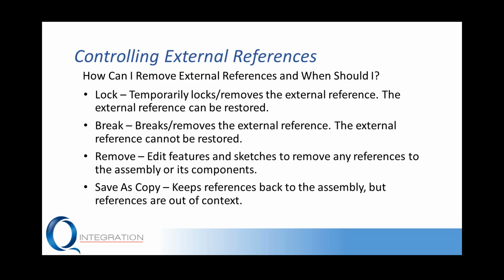So how can I remove these external references? Well, we already took a look at a couple there. We can lock to temporarily remove the external reference. This is kind of nice in case I want to take a look at how this part may behave if I don't have the external references there. And then at any time I can go back and restore that. We can also, like I said, hit the easy button and we can break those external references right through the list external references dialog. These cannot be restored. This is a permanent break.